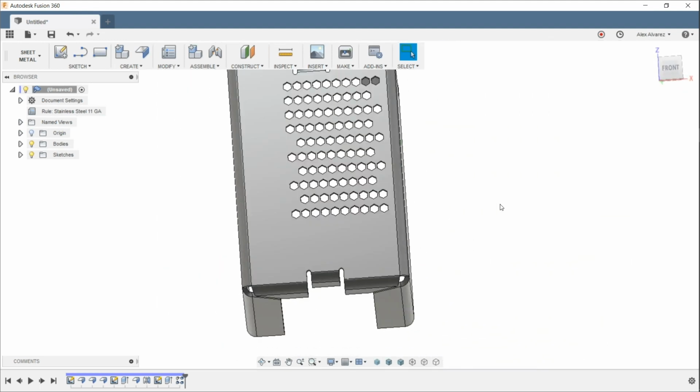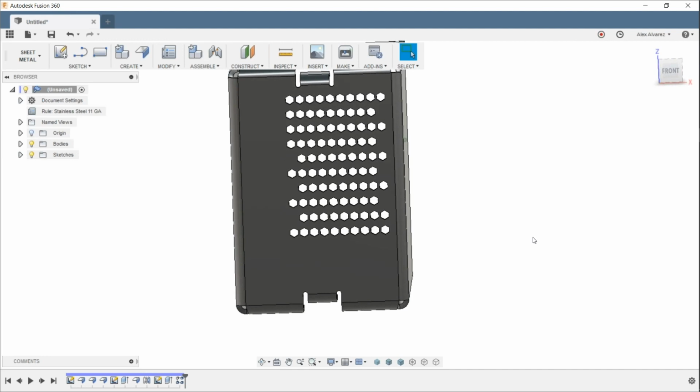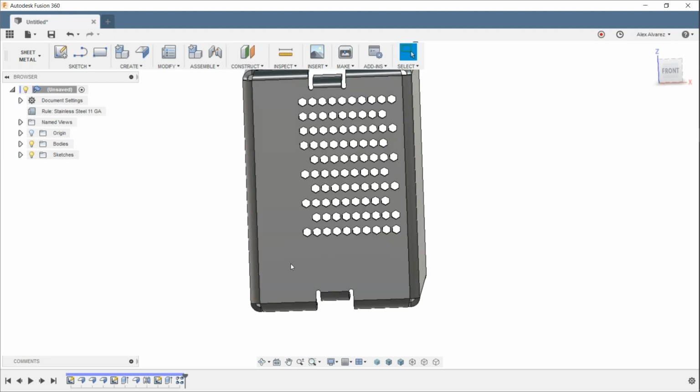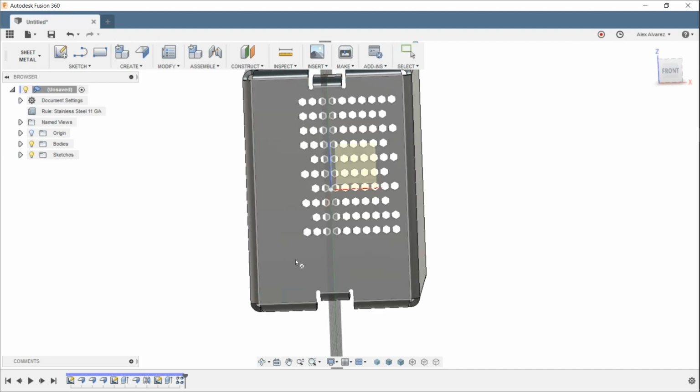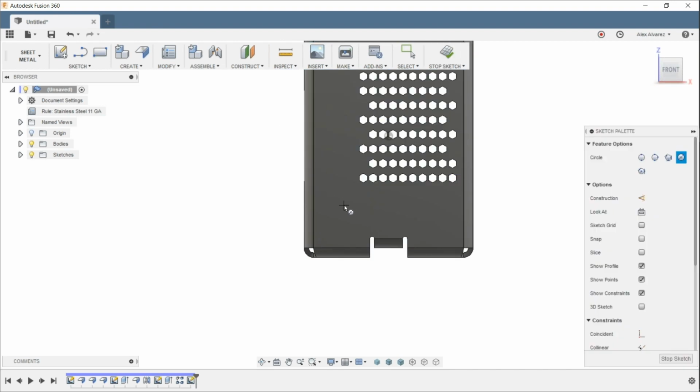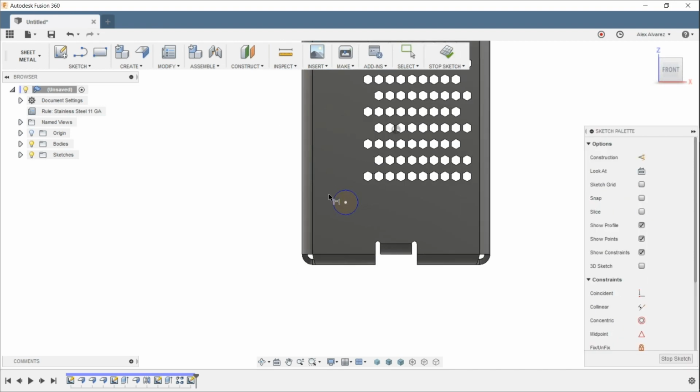our cutouts, right? So really the last step here then is creating that hole. Right? So again, let's create that hole here. C for circle. And then notice also that I'm not having to create a flat pattern, right? Or unfold it and start refolding it. Again, I'm working on the same face that I started off with, so that's always going to be my stationary face.